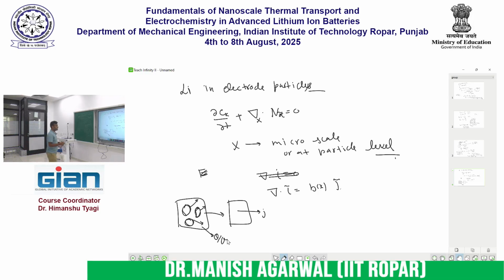Okay, and I is now given by minus sigma, but this is actually a homogenized quantity, times del phi. This conductivity is different from the usual conductivity, because now it is a homogenized conductivity, because the domain consists of the electrode particles and also the binders, which have very poor conductivity.